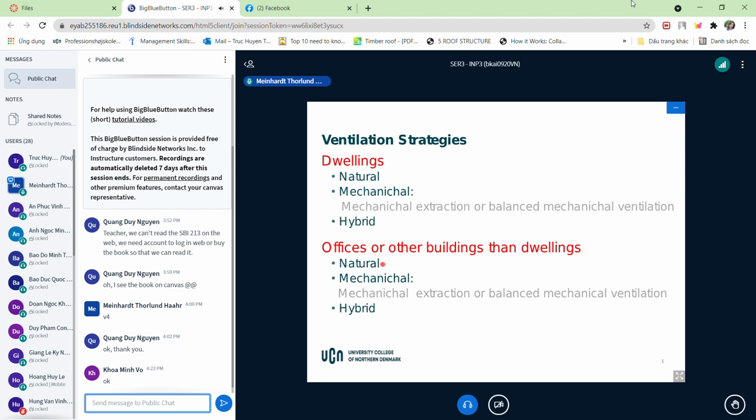And also, when you're doing natural ventilation, you will have a difficult time achieving the building energy frame efficiency, because natural ventilation also includes heating up the building in the winter time. 20 degrees air is going to exit the building, and minus 12 degrees during the worst part of winter will come into the building, and this temperature difference needs to be reheated by your heating system.